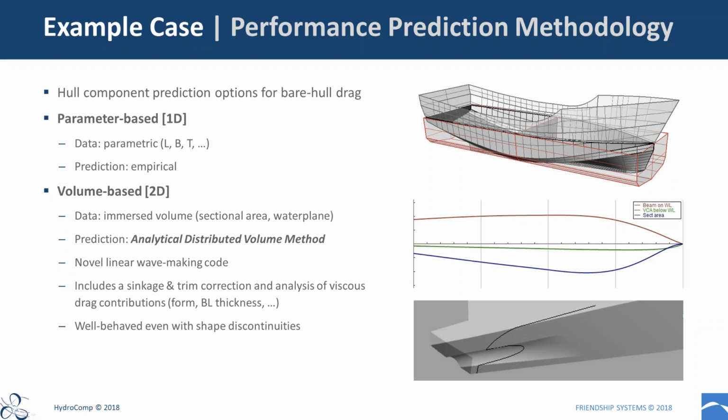So the use of the Telfer coefficient, which normalizes resistance by vessel displacement, is a great way to improve the effectiveness of this kind of analysis, because now you're looking at a normalized resistance. In this particular case, our final hull was a few tons larger than our initial parent displacement. One way to resolve that is, once the optimum shape is resolved, we can just use a geosim scaling to bring it down to the final displacement if we felt we needed to.